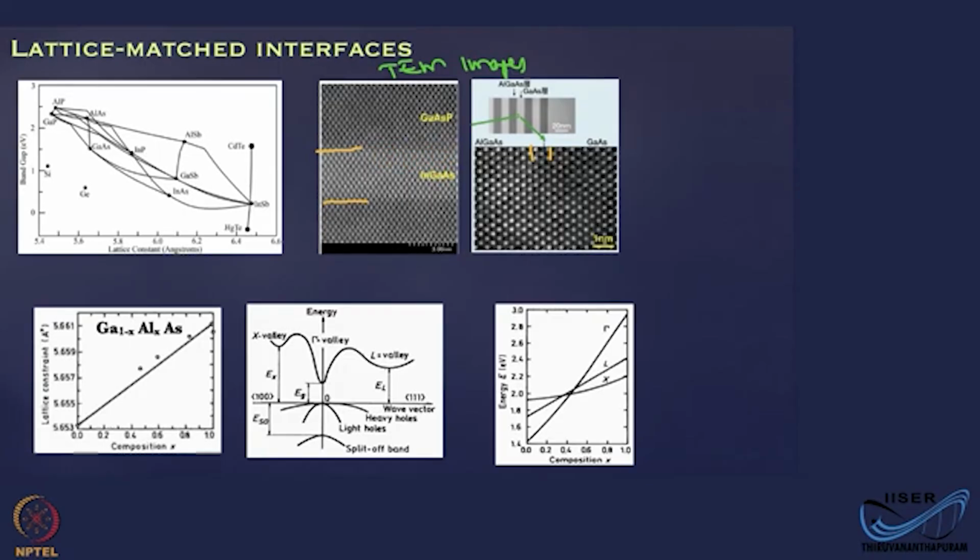If you ignore that those are made of two different sets of material elements, and just assume that those are all lattice points, they're just continuous. There is not much mismatch between this system and that system. That means the lattices of these two materials are so identical that there is a perfect lattice matched interface.